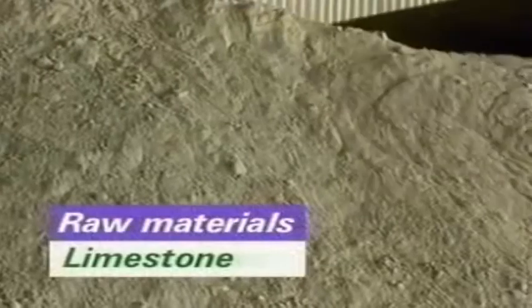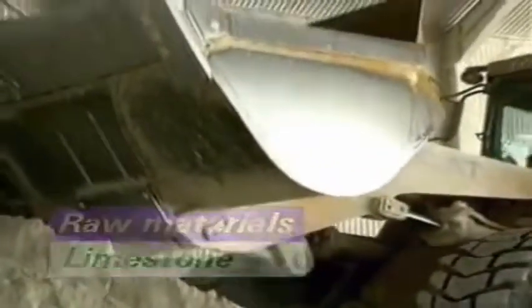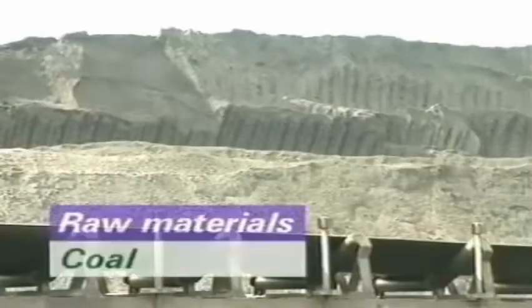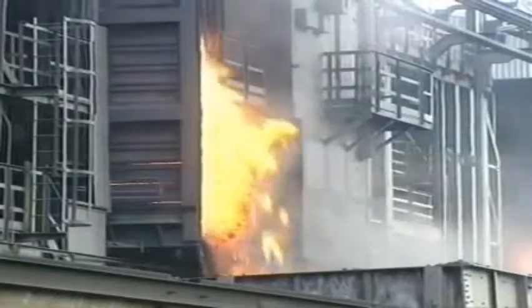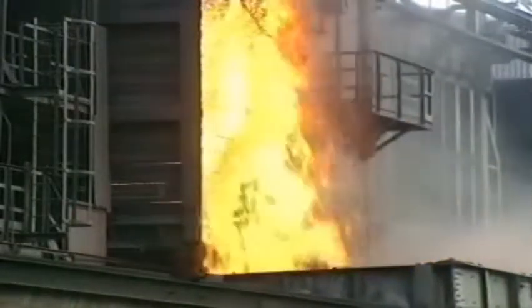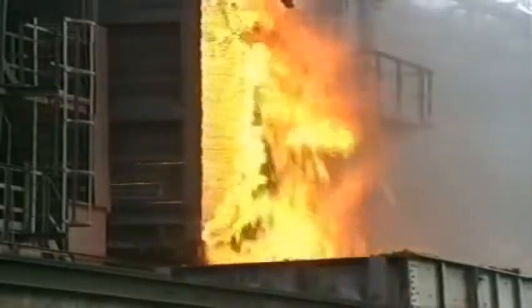Limestone is quarried in the UK and is delivered to Scunthorpe by road. Coal is imported. The coal is converted to coke by heating for 18 hours in an oven. Gases, tar and ammonia are driven off, leaving an impure form of carbon.